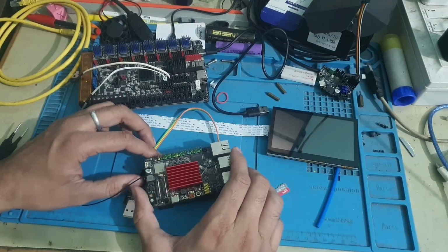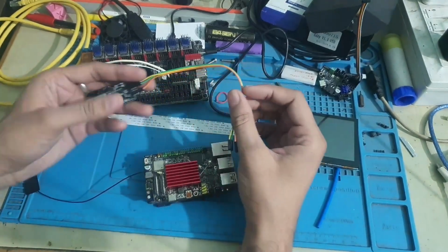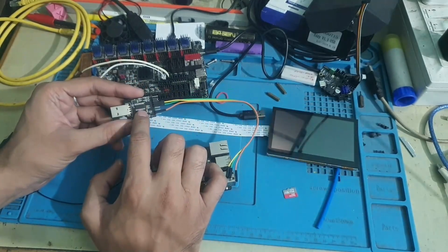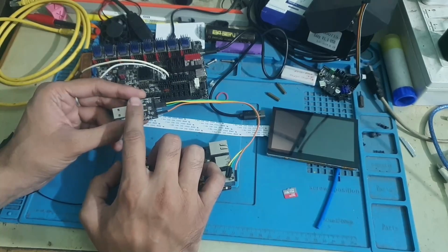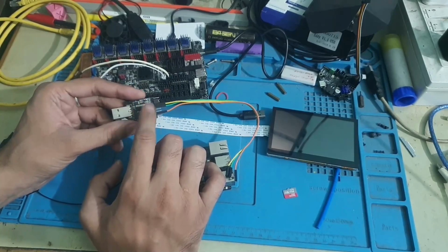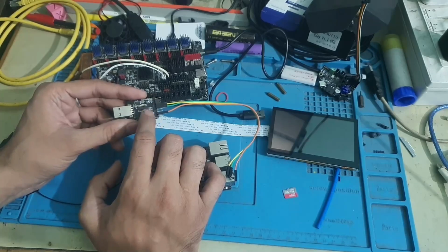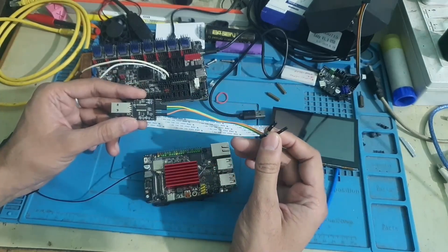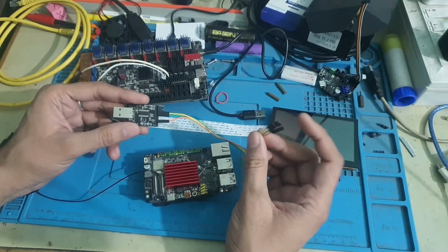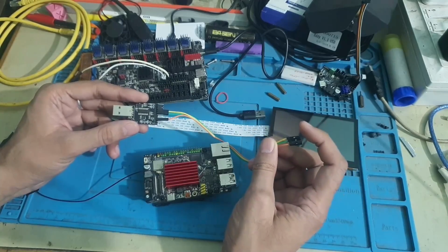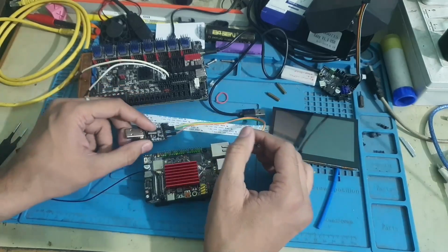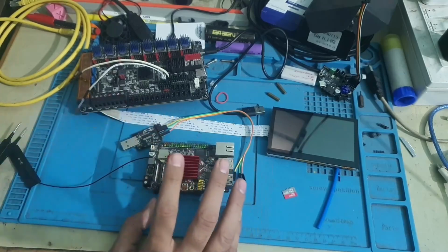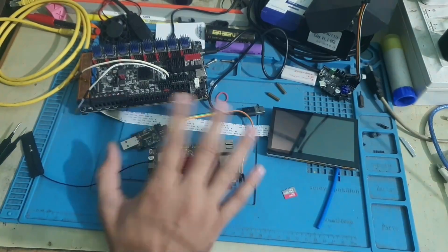If you're not able to access the LAN cable somehow, you need a separate device, like a CH340 serial, so a USB to UART serial connection. You need communication with the UART pins. So you need to connect TX, RX, RX, TX and a ground cable to communicate between the Pi and the computer, so you can access it with the terminal.